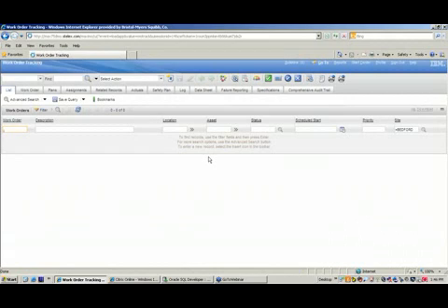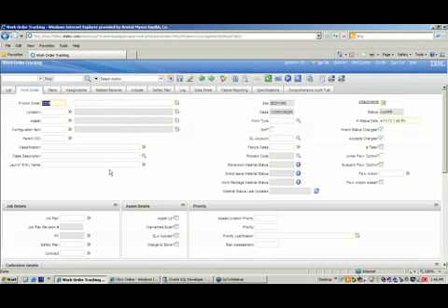Okay, we're going to actually create a work order here, and we're going to bring a data sheet into the work order itself. The process again can be either manually created, or you can actually have the system generate it through PM. The WOGEN process will automatically generate a work order, and because of that association of the asset and the data sheet in the job plan itself, it will copy the data sheet right into the work order itself.